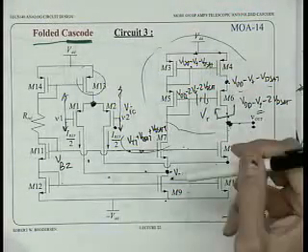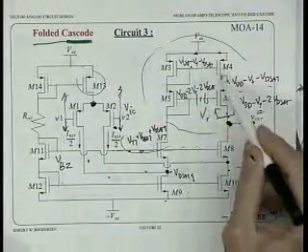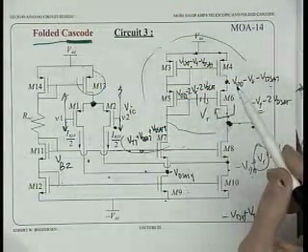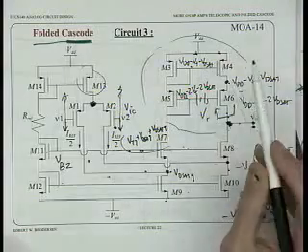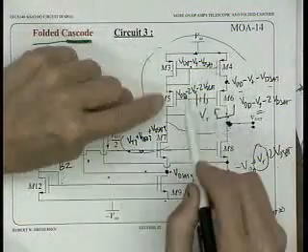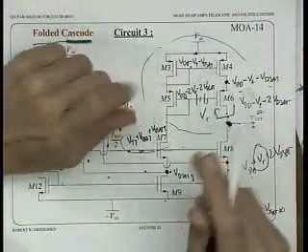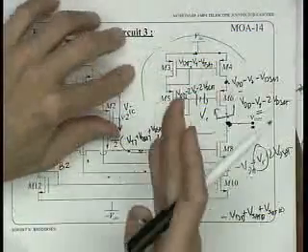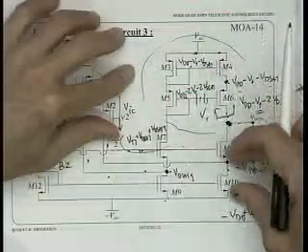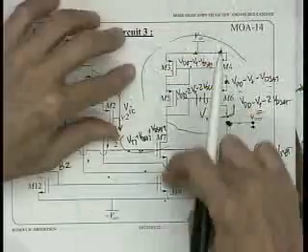When you're calculating the necessary voltages in the current bias M3, M4, M5, M6, are you assuming that they're all identical transistors? Right now I am. Really what has to be the same is 3 and 4 have to be the same, and 5 and 6 have to be the same. But other than that, I assume this is matching this. There's that balancing, but there's lots of flexibility the other way.